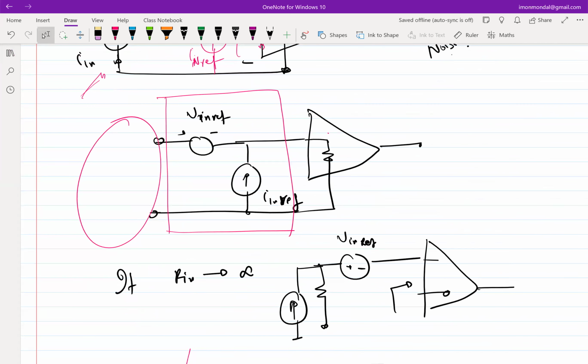and then we were trying to see under what condition one of the voltage and the current source can be neglected. We saw that if the source impedance is zero, that is, you are driving your amplifier with an ideal voltage source, then the input referred current noise, In ref, will get shunted through that source, and it will not be necessary. You can as well model the entire noise with Vn ref.